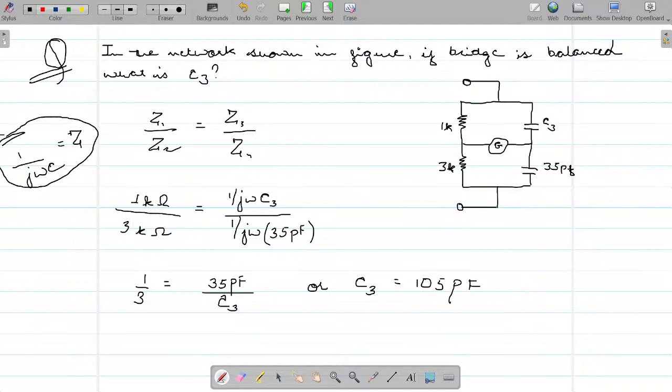And I think I have on purpose included a lot of questions based on capacitances just so that you don't make this silly error. What generally people do is they replace the impedance by the capacitance itself, but it will not be true. Why? Because in case of capacitance, the impedance is in inverse ratio to the capacitance. So there is no direct relation. You need to make sure that you do not make this mistake. It's a very easy question.